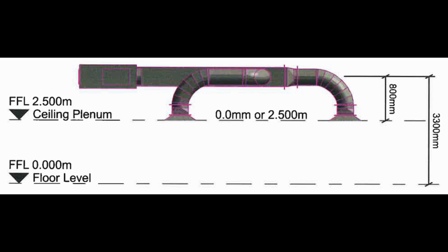Multi-story design and the clipboard. Many components need to be repeated across multiple floors. Revit's clipboard tools allow you to copy elements, paste them aligned to selected levels, and duplicate them across multiple stories at once. This is extremely useful for repeating equipment layouts, riser components, or standardized room configurations.